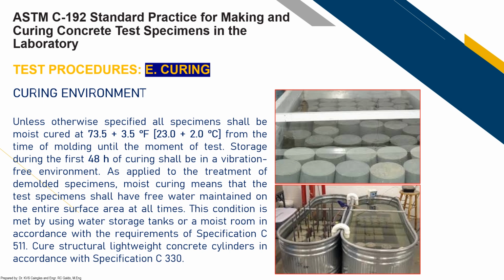So what's going to happen after you have demolded your concrete specimen, after you have removed it from the mold, is you are going to put it in the water storage tank, and the entire height of your cylinder, or the entire specimen, cylinder or beam, needs to be covered by water in your water storage tanks. That is to maintain the temperature of your specimen. Okay.